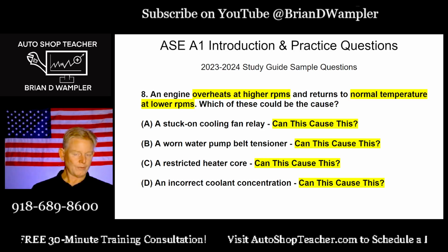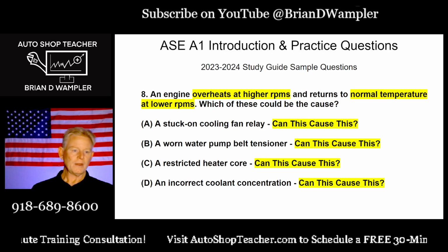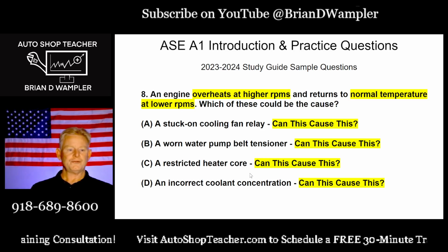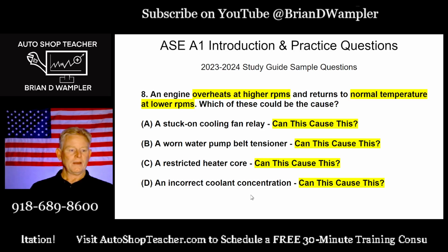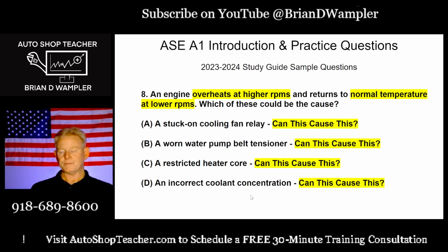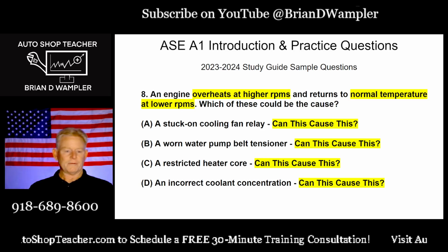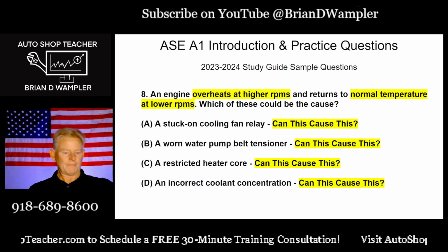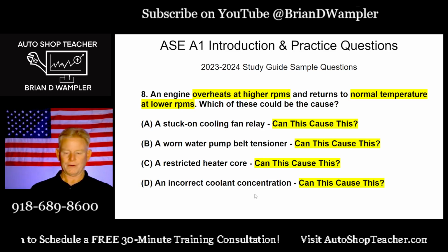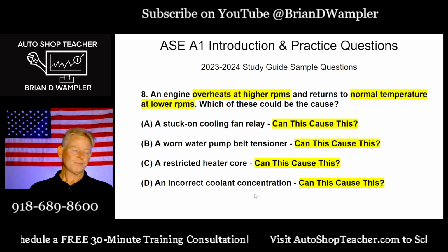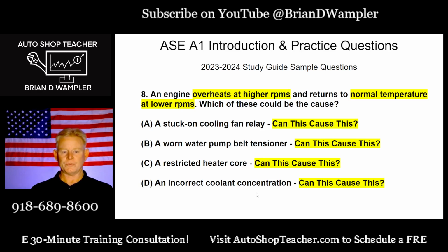And does the heater core, which is used to provide heat to the passengers inside the vehicle, change or affect this high RPM versus low RPM? And then an incorrect coolant concentration. Now, we don't need to sit and debate if it's 100% coolant that they got from some third world country. No. This answer just says incorrect coolant concentration. So they didn't mix it 50-50, it's 60-40 or whatever you want to say. So don't add into the answers when you're reading these.